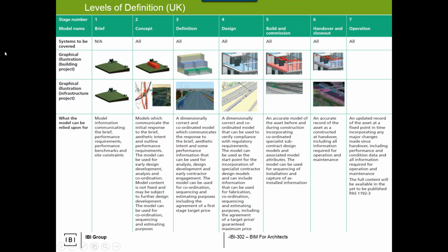And again, they define the level of definition, which corresponds to North America's schematic design, design development, contract documents, etc., or corresponding to 30, 60, 90, 100. So I've done some slides in the past where we actually compare the two, but conceptually know where you are within your project, whether you're in concept, design, contract documents, construction, and ensure that the quality of the information as well as the quantity of information corresponds to the phase of the project so that you're not going above and beyond the budgets as well as the scope requirements for the specific project.